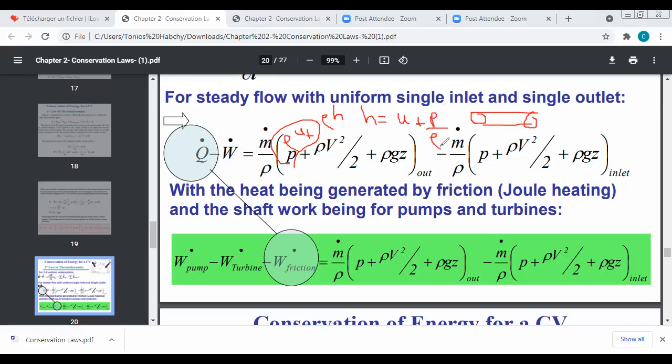In general, if I don't have a large increase in temperature, so if T is nearly constant, then I can say that the variation of internal energy across my cross sections will not have a change. Or if I have negligible variation of temperature, so for small delta T, if I have a fluid moving, and of course I'm talking about a single phase, I don't have change in phase, because when you have change in phase at constant temperature, you can have variation of internal energy.